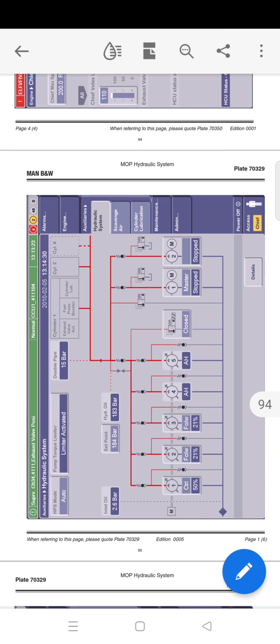Now guys, go to the auxiliaries. In the auxiliary section, the hydraulic system, scavenge air, exhaust gas bypass if installed, and the cylinder lubrications are monitored in the auxiliaries main navigator. So from each menu the operator can control and monitor these systems: the hydraulic system, the scavenge air or exhaust gas bypass system, the cylinder lubrication.